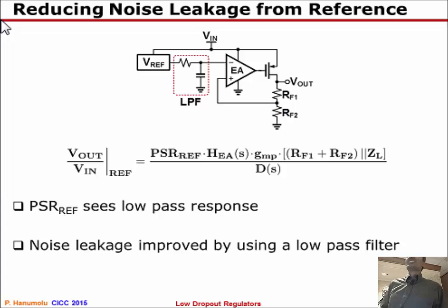Number two, if you are thinking in terms of a PLL, I'm presuming that this LDO is supplying the oscillator, in which case the low frequency noise is rejected by the PLL loop itself. Unless you have a PLL loop whose corner frequency is in the vicinity of the flicker noise corner, we'll have to do something special.